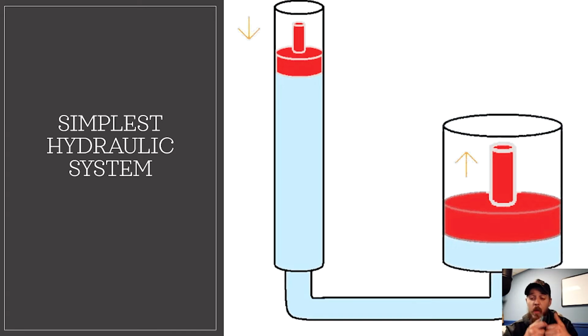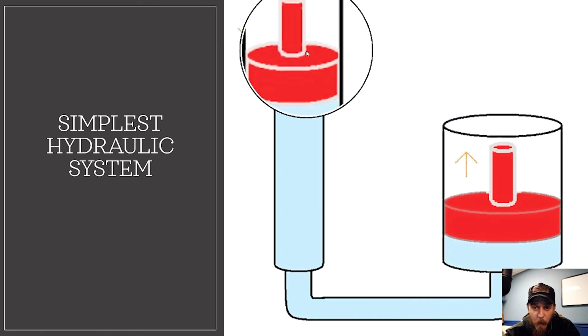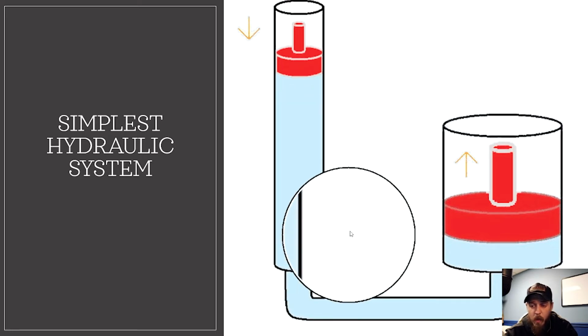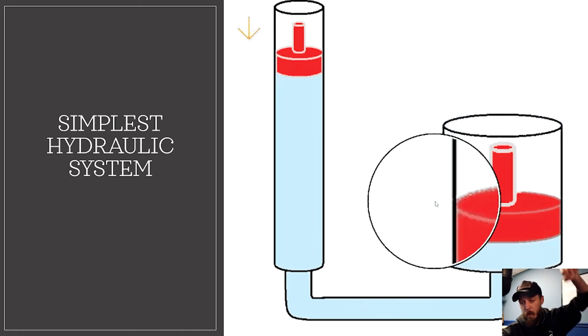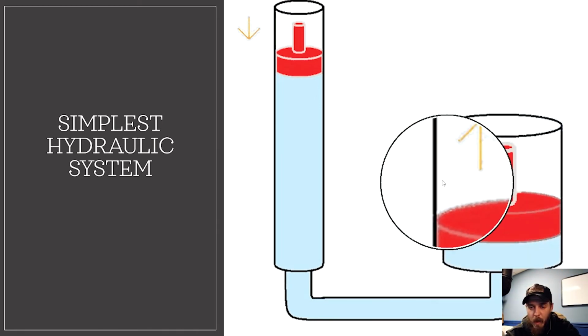A regular pump jack, a bottle jack, a floor jack: you take a smaller piston and you pump it, generally with a longer stroke, meaning our floor jacks and bottle jacks have a lot of stroke here for a little bit of movement on the lifting end.